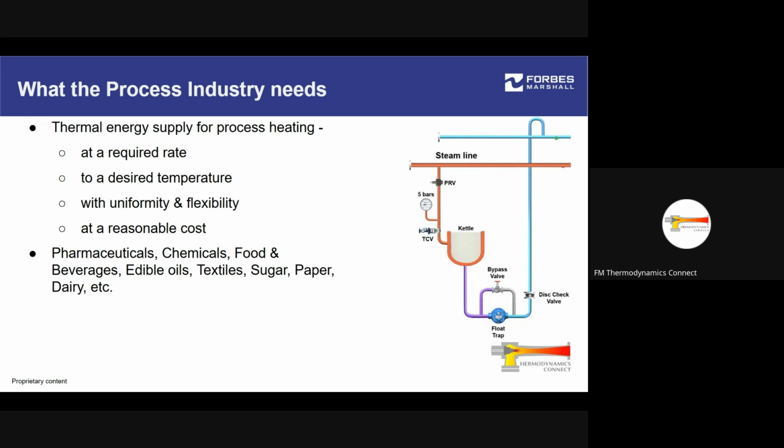But the moment it is a single phase system, whether that is superheated steam or single phase water in this particular case, subcooled liquid, what we call, in both of these cases, it is going to result into poor heat transfer. Okay. And if that condensate ends up getting backed up, again, you have differential temperatures in different segments, you have poor heat transfer rates, increased batch times, what have you. So that needs to be removed very effectively.